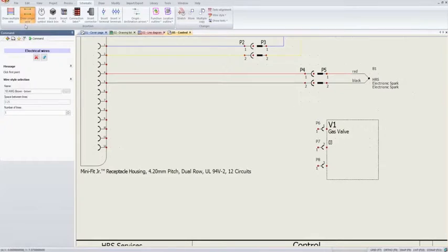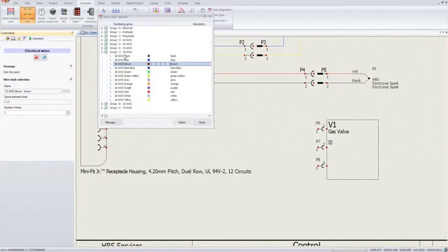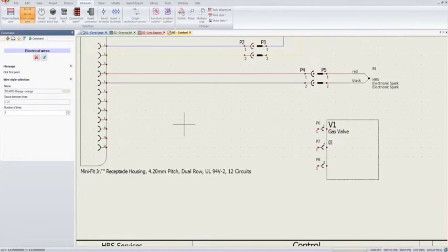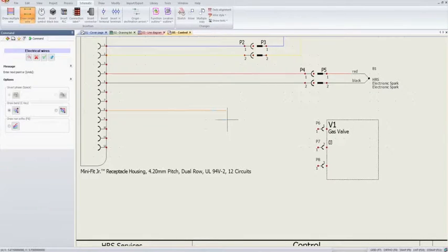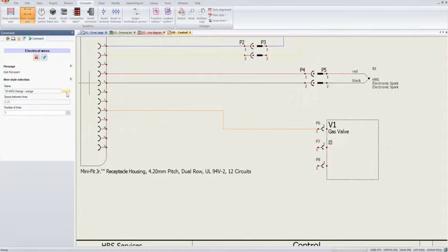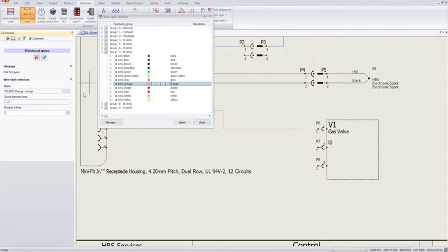You can go ahead and go into single line wire and then choose the one that you want. In this case, I want to use an 18 gauge for this guy. So in this one, I'm going to use the orange for our first one. So I'll connect it up to my 8. And you'll even notice subtly that there are these inference lines, very similar to SOLIDWORKS, which pretty much guides you along, creates your horizontal and vertical so that it lines up to the pins correctly.